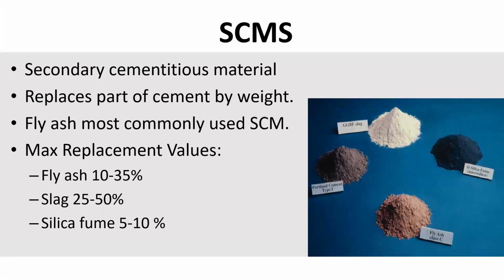You could actually take out a little bit of Portland cement and add fly ash. The same thing happened with slag. Slag is from the steel industry, and they said, aha, I can take this byproduct from the steel industry, regrind it, and put it in concrete, and it works really well. Both fly ash and slag are normally a lot cheaper than cement. Cement's usually one of the highest-cost ingredients because you're fully manufacturing it.